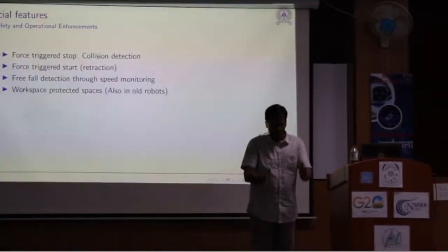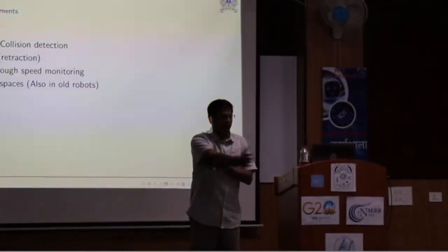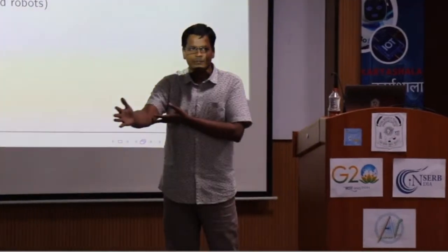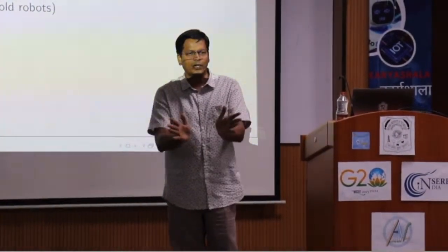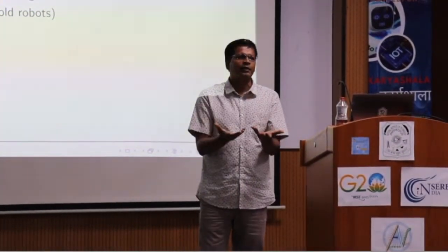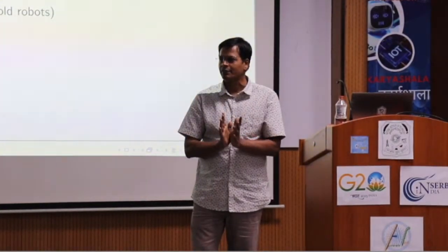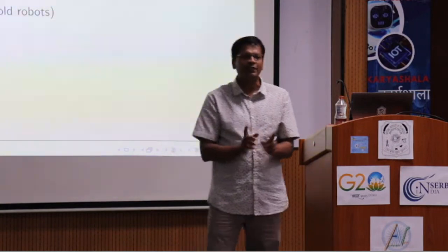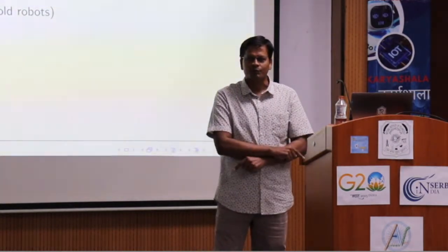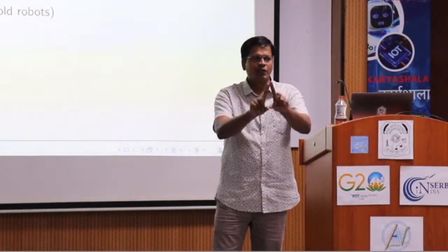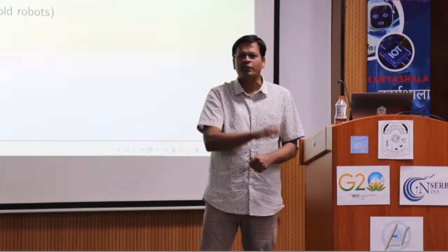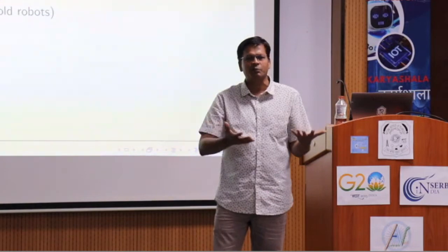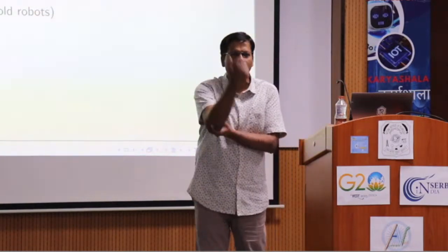Because you have a table over here, you want your robot to operate from here to here, or here to here. So you can safely monitor that angle. You can exclude that motion from your motion list. You can have that in joint space. You can have that in Cartesian space also. A Cartesian block, you can always define in space. Your robot will never go there. In case of cobots, which have full knowledge of their geometry also, even your arms will not go there.